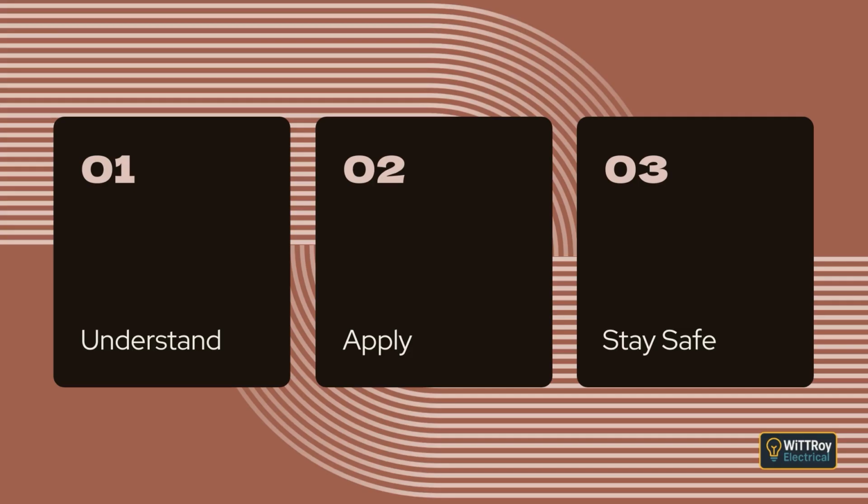Clause 3.7, Electrical connections. This clause introduces the requirements for how conductors must be connected so that electrical continuity, insulation integrity, and mechanical strength are maintained throughout the life of the installation. Clause 3.7.1, General. This clause explains that every connection between conductors, or between conductors and equipment, must provide a reliable electrical pathway, proper insulation, and enough mechanical strength to stay secure.